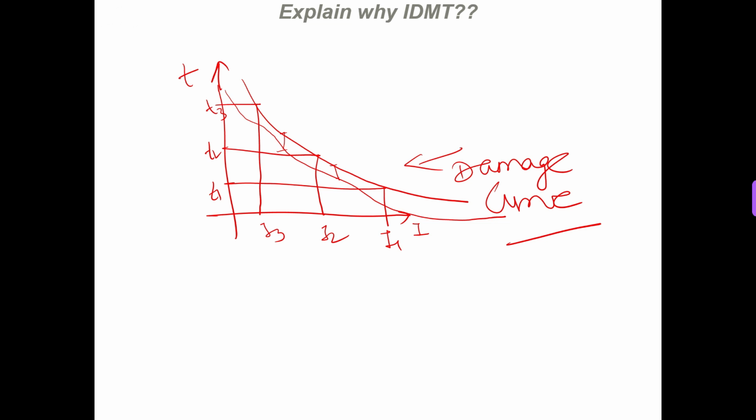So we have to use a certain type of curve for our protective relay. If the damage curve is like this, we have to use an overcurrent characteristic which matches this curve. Depending upon these different types of damage curves, we have different types of IDMT characteristics.